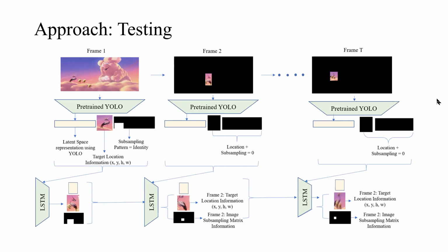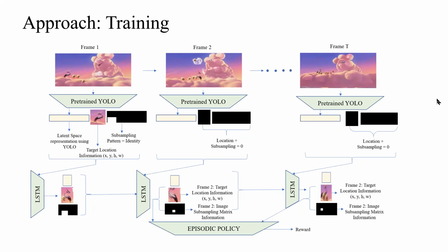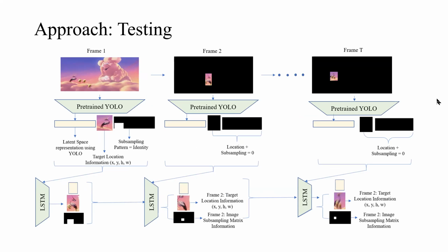This is our testing stage. So basically, it's more or less the same processing through the pipeline. The only difference is that here we no longer extract features from the fully sampled frames, because, as we know, at test time we are trying to optimize the sensor energy efficiency, which we can do if we manage to switch pixels off outside of the region of interest. So that's the reason why, other than the key frame, the frame in which the fully sampled frame is available to the sensor, we just extract features from ROI or subsampled images, and that's the only difference.